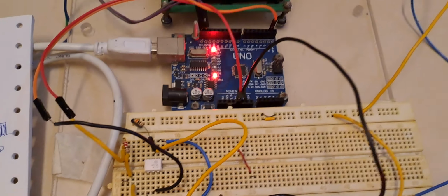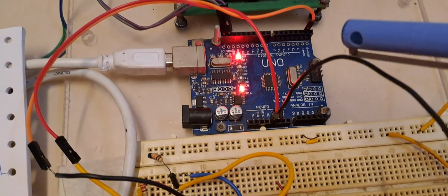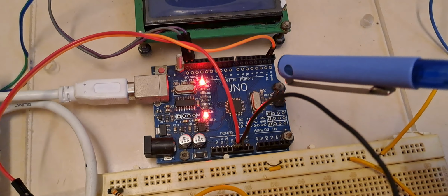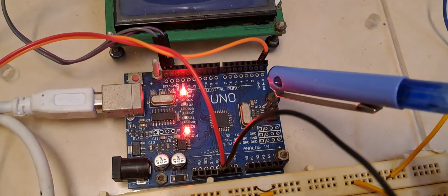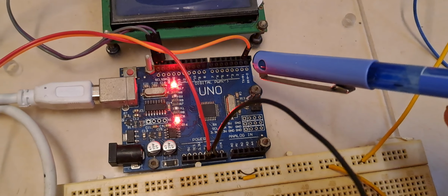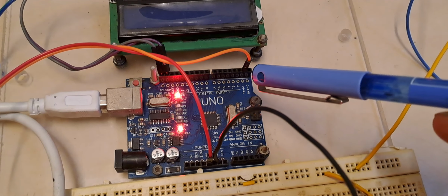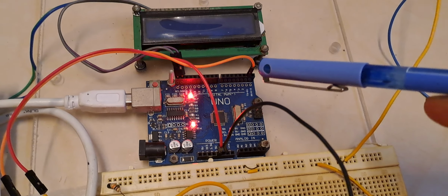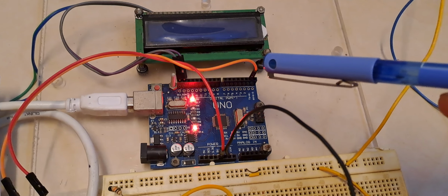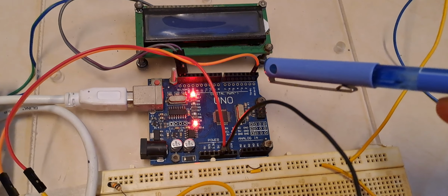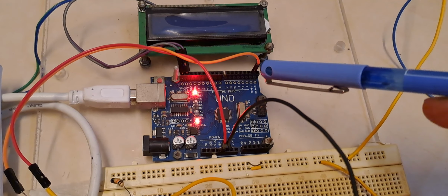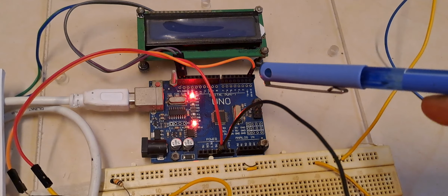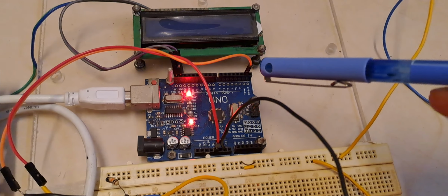seeing the results. So as you can see, this is the transmitter end. In the transmitter end, here you can see Arduino Uno is transmitting data. You can see from the TX pin of the Arduino Uno, I am sending the data. So this is the 9600 baud data that is being sent. This data has to be received by another Arduino Uno, and we will be seeing the results in the computer console. So as you can see here, this data will be modulated with a 48 kHz carrier signal, and we will demodulate the carrier signal and we will be getting the final data.